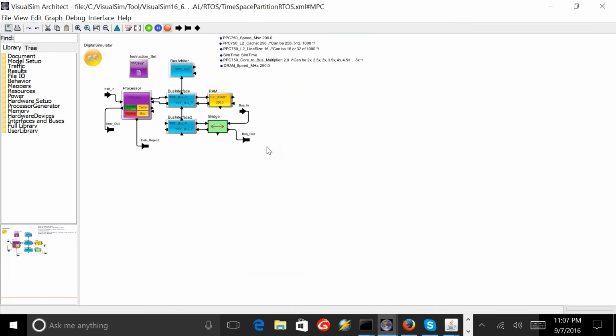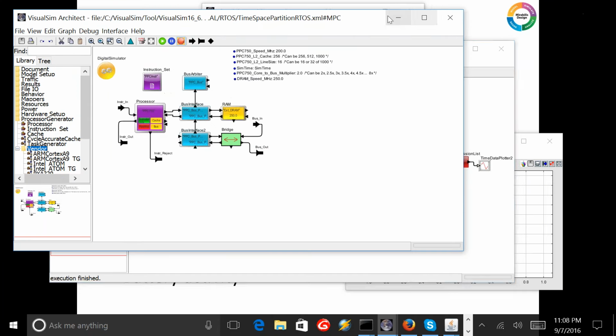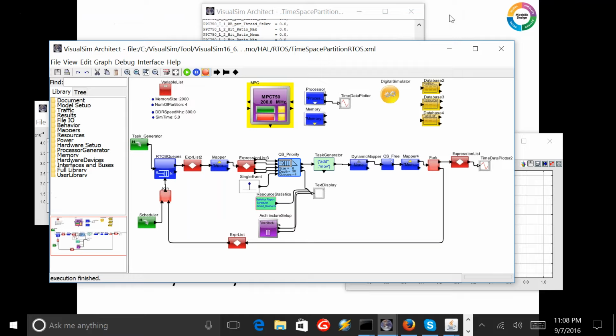Now, one of the key things that can also happen is, if I go back into the RAD750 platform here, not only can I keep this RAD750, but I could possibly even extend it by adding other vendor products. We've got over 100 processor families, so you can actually add other processors. For example, you can offload some of these to, say, a Xilinx Virtex-4, Virtex-5, or a Zynq 7000 family. You can also look at other processors for certain tasks that are not that radiation impacted, and you could add those and see how the system behaves. So this system is also fully scalable to handle additional patterns or additional hardware elements in the particular system.